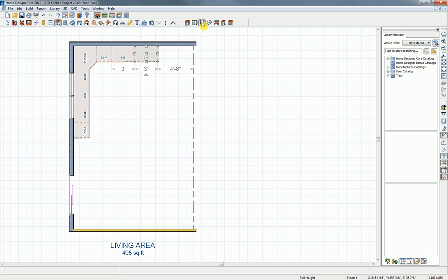All right, let's get into the full height and just drop in a full height here. And let's change that to 42 inches. All right, let's get into a camera view. This time we'll use our full camera. With the full camera, you click where you're standing and drag to your focus.